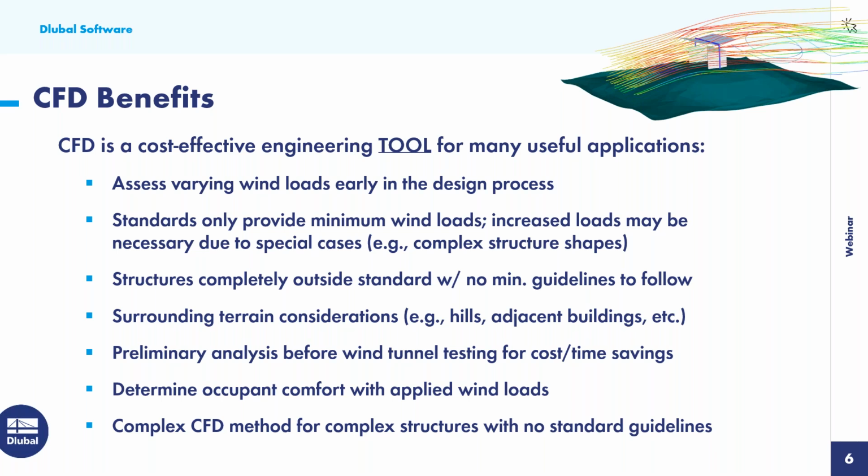And notice that I have put emphasis here on the word tool rather than an approved method according to the standard. So CFD allows us to assess varying wind loads very early on in the design process. We can take our structure, apply the CFD numerical wind tunnel, and see the impact very early on in the design process to see what type of structure modifications we might need to make.